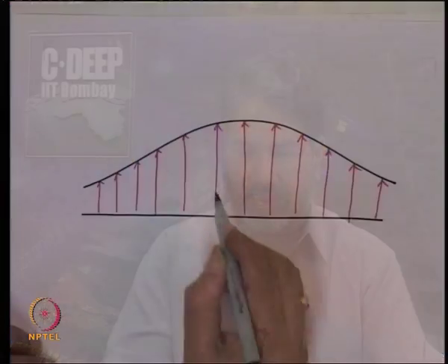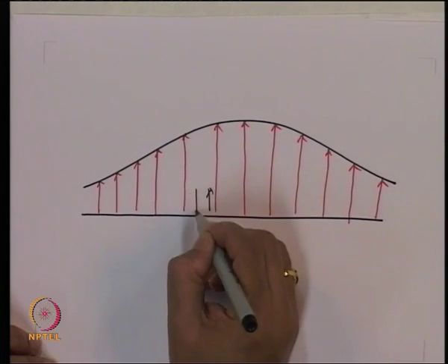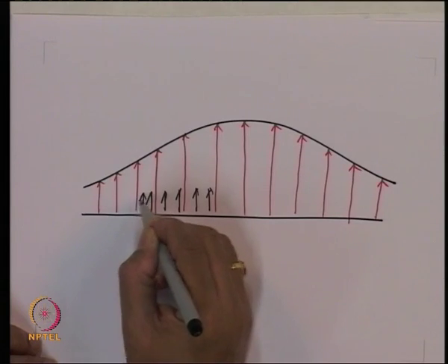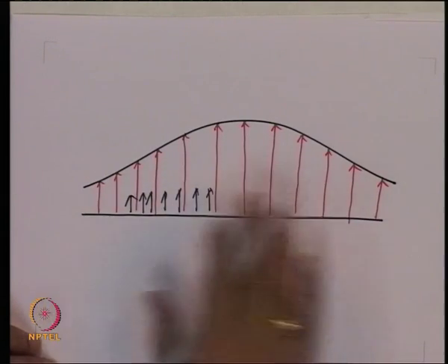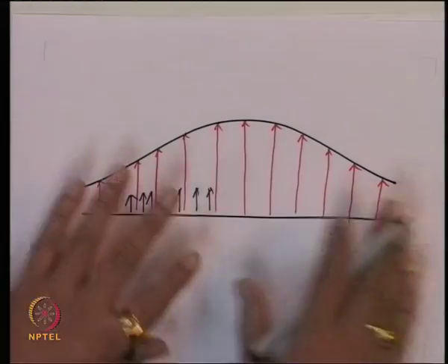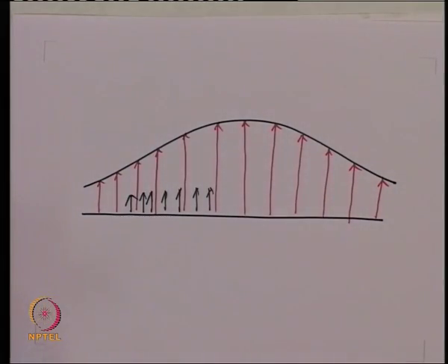Each one is modulated in an amplitude modulated fashion with the modulating signal. So, one can say that each of these carriers would have its own sidebands, and that is the reason the sideband information is completely masked, because you have a distribution and sidebands are completely submerged inside this.